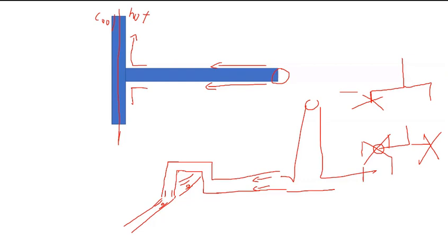And this one is a similar idea to this one too. So you change the flow direction, not in the horizontal direction, you make it in the vertical direction, and it will not 100% fix the shear heating issues, but it can reduce the shear heating, the flow imbalance caused by the shear heating. It can reduce it.